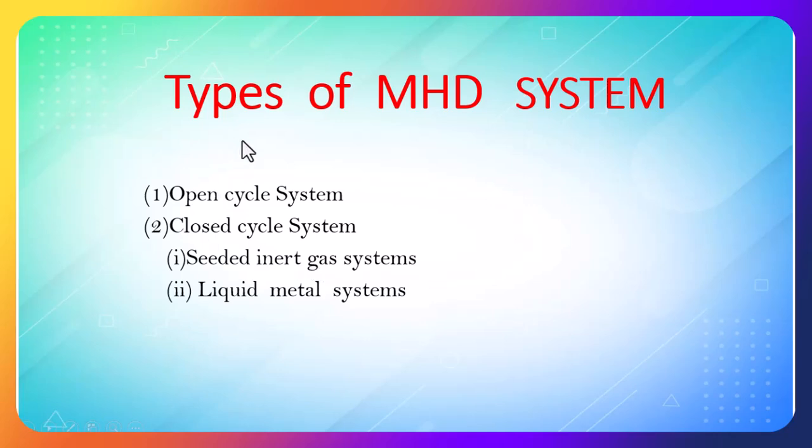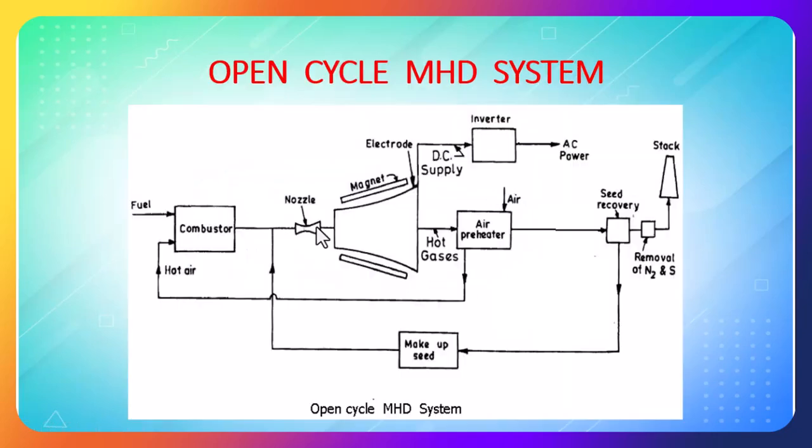Here, when you go for an MHD generator, there are types called open loop system and closed loop system. We will see what is open loop and what is closed loop. Initially we start with open loop. Again, you are getting heat as a byproduct of your process, where you are going to heat the ore, or any other way by which you are getting heat as an output. That heat we are not going to leave to the atmosphere; rather I will take that heat and try to heat my air and make my air ionized.